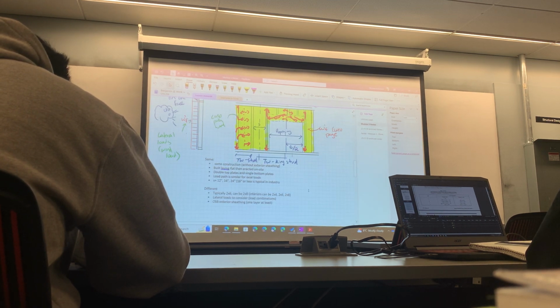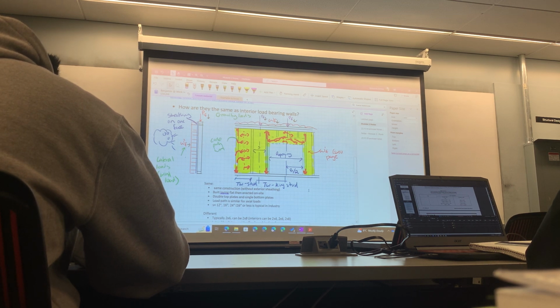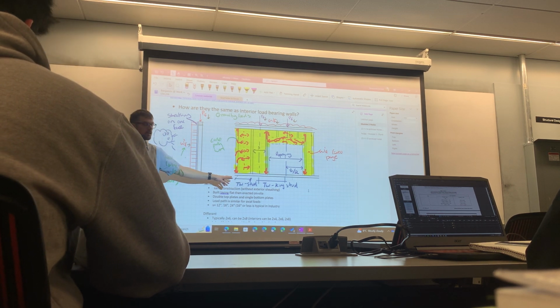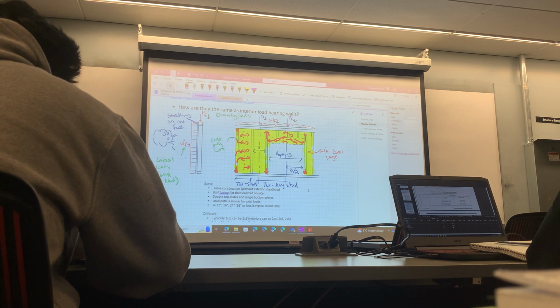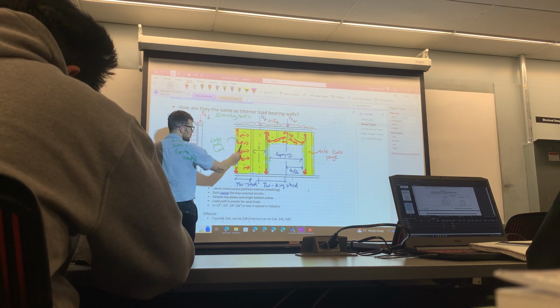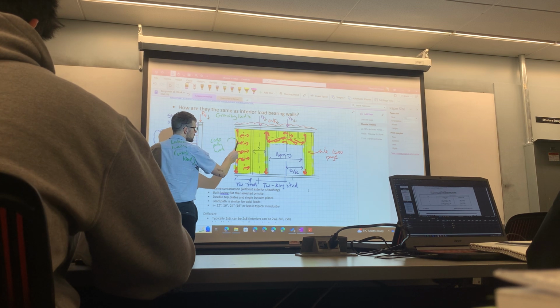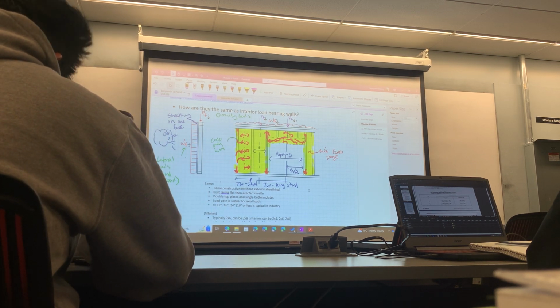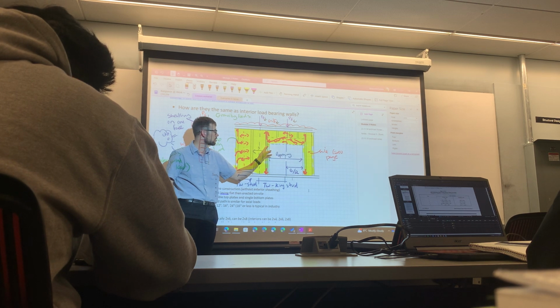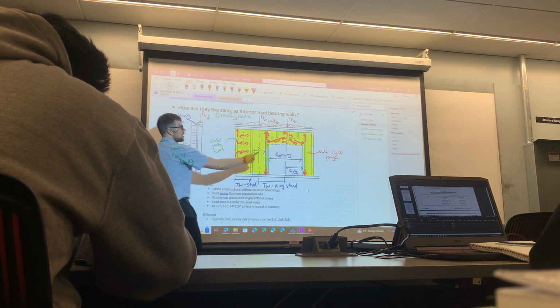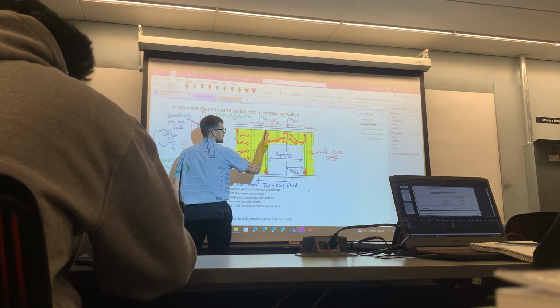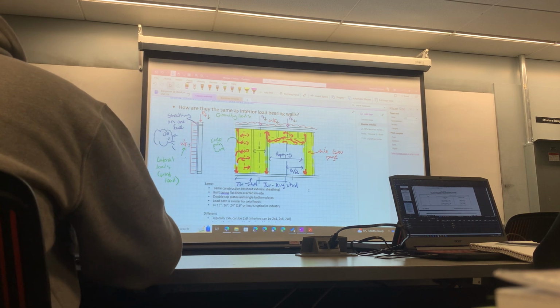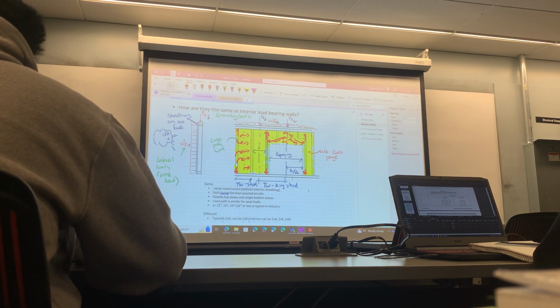We're not going to have to do this in the course. I might ask you some test questions, like draw the load path. Basically I just want you to redraw this. I'll say draw the load path for the studs, and I want you to start in the middle of the studs, work into the studs, and work yourself into the top plate. And if I say draw the load path for the king studs, same thing: start at the top of the wall, get it into the header, the header transfers it to the king stud, which transfers it to the floors. Once it's in the floors, you can consider it in the building, because we haven't talked about lateral resisting systems in the building. Any questions on that?